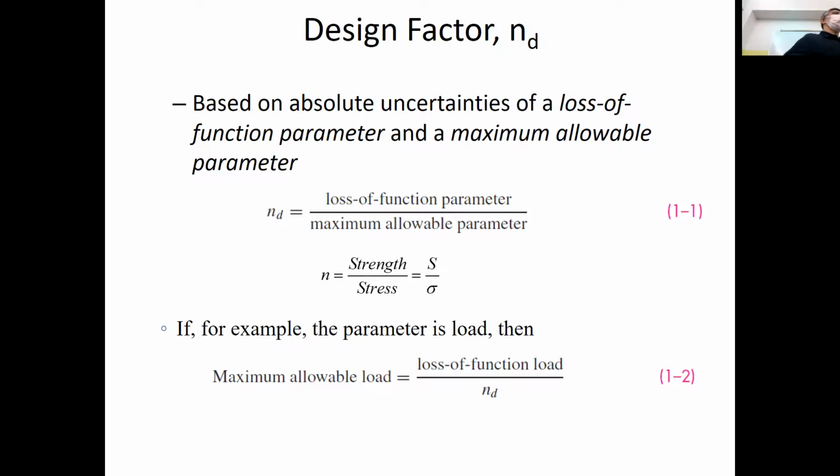For our machine elements, 1.5 is a typical design factor for just standard machine elements. But really it varies from one industry to the other, and some are going to be dictated by the type of industry or your client, depending on whom you are working with. So this is something you're going to have to look up when you are designing special parts. But I really want you to keep in mind this understanding.